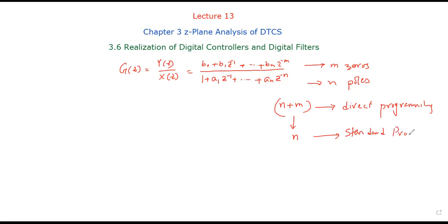Different other structures are available, and basically those are introduced because three kinds of error are present. The first error is the quantization error that we have seen, because we have a limited number of digits, so a limited number of discrete values. Whatever the analog signal is, it has to be fit into those discrete values.